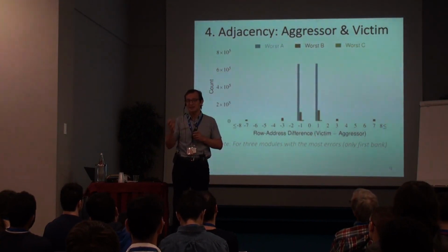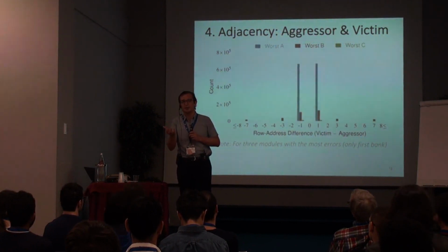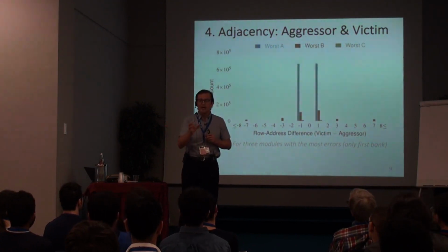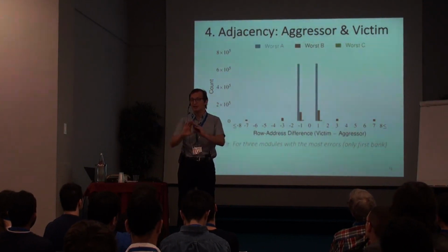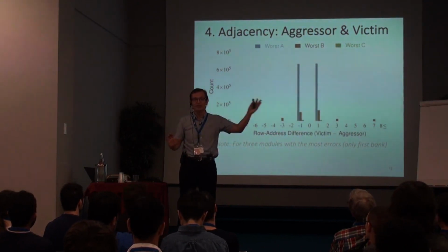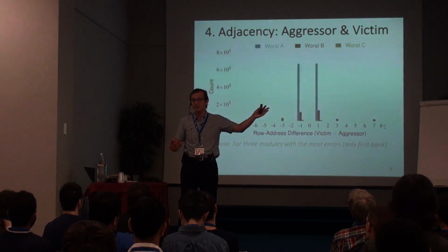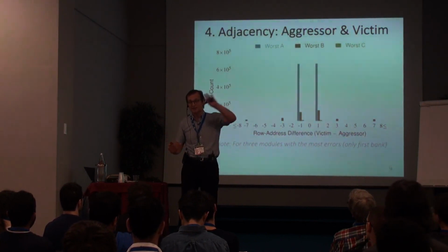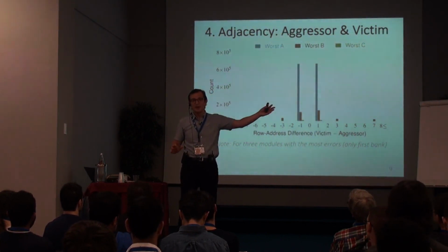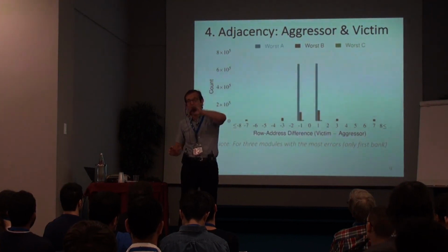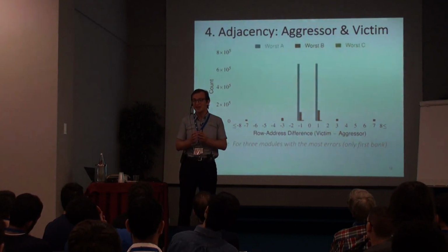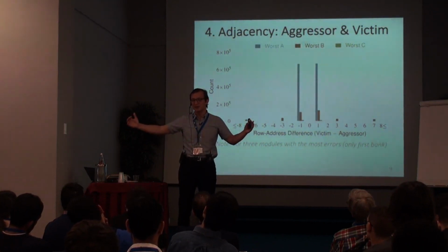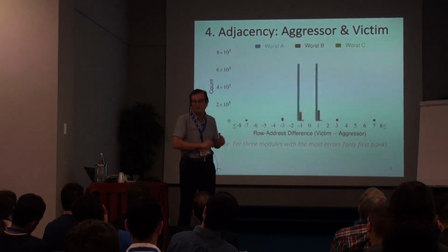So actually people have been proposing, why don't you have more rows inside DRAM that are not used for anything, and whenever you discover errors in some other rows, remap the rows that you were using to these other spare rows. If you have systems like that, then you have a lot more spare rows, and this figure might change.